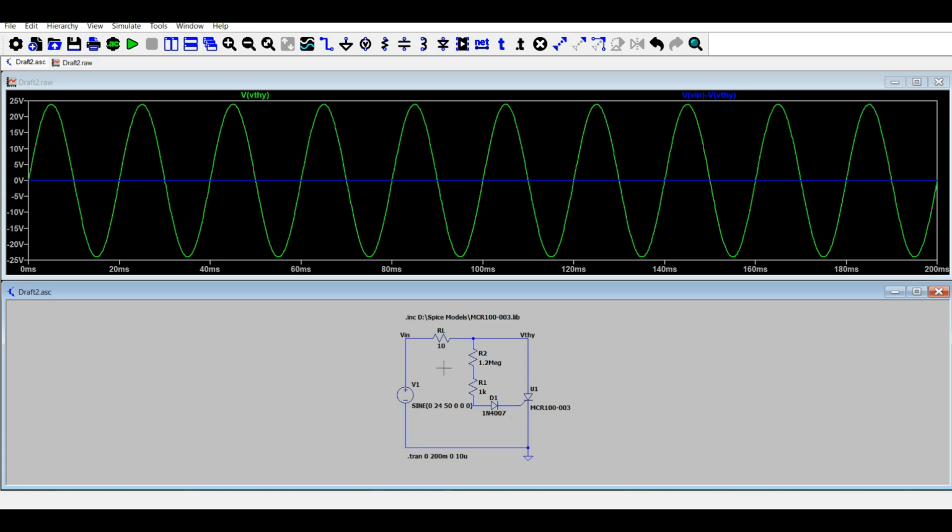So from this specific circuit, we can conclude that the maximum firing angle achieved is 90 degrees, or it is less than 90 degrees, right? So in the next video, I'll be posting another configuration that will also have the gate triggering part being fed from the main input source, but the firing angle range would be approximately up to 180 degrees, right?